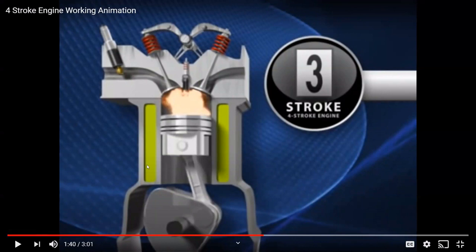And you can see that as the fuel is igniting, the piston is already moving down, which means that the volume is already changing. But the ignition probably finishes well before this piston gets back down to its bottom position. And that means you can approximate this as if the ignition happens over such a small time period that the volume hasn't changed at all.